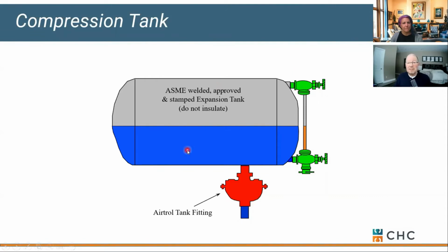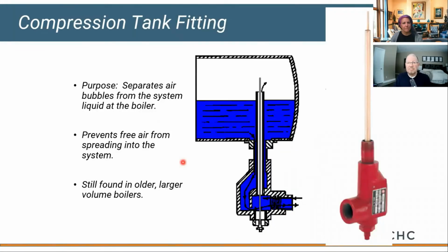The other downside of this style tank is the fact that it's got to be elevated in your mechanical room. It's normally a high spot. So seismically, it can be a challenge. You got a lot of weight over your head. And most guys just don't understand this. It's a very simple operation, but again, it just works on a balance of air and water.